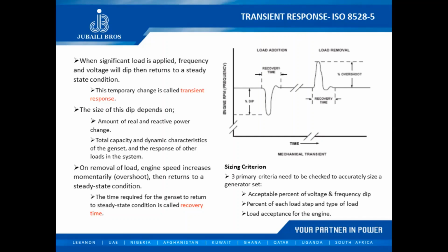Muhammad Qadir is asking, in the data sheet of alternator, there was temperature rise class H125 and H165 for the same model. Can you please explain the difference between the two subclasses? Yes, Khalid. Okay, so the one that's 165, or actually 163, that's the standby rating of the alternator. What I was discussing is the continuous rating of the alternator in two cases. In a case that's class H temperature rise, and in another case that's class F temperature rise. However, what you saw at the end, the 163, that's the standby rating. That's typically 10% more than the continuous rating of the alternator.